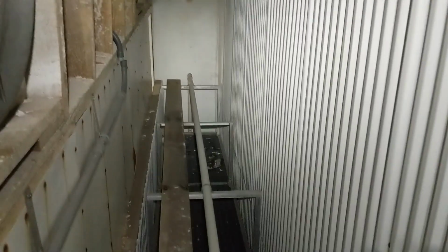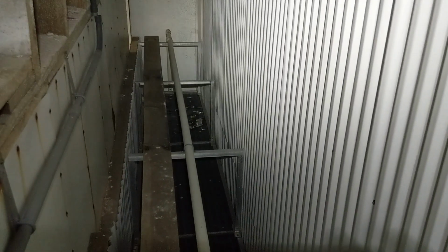Confined space incidents are often fatal because hazards can develop quickly and rescue is challenging. As a refrigeration technician, never enter a confined space without proper testing procedures and authorization, even if the task seems quick.